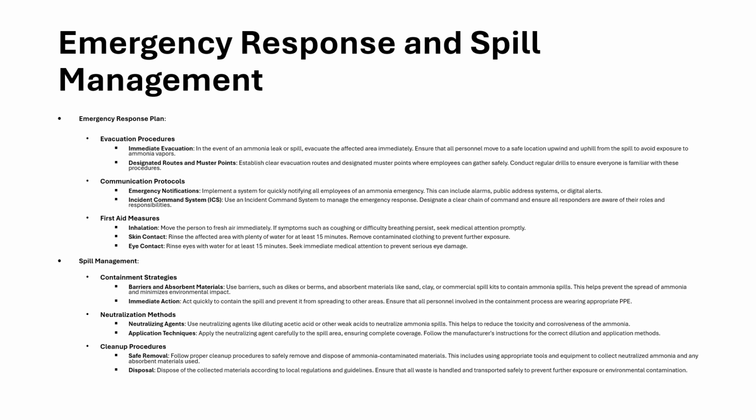First aid measures. Move the person to fresh air immediately. If symptoms such as coughing or difficulty breathing persist, seek medical attention promptly. Rinse the affected area with plenty of water for at least 15 minutes. Remove contaminated clothing to prevent further exposure of the skin. Rinse eyes with water for at least 15 minutes should ammonia make eye contact. Seek immediate medical attention to prevent serious eye damage.